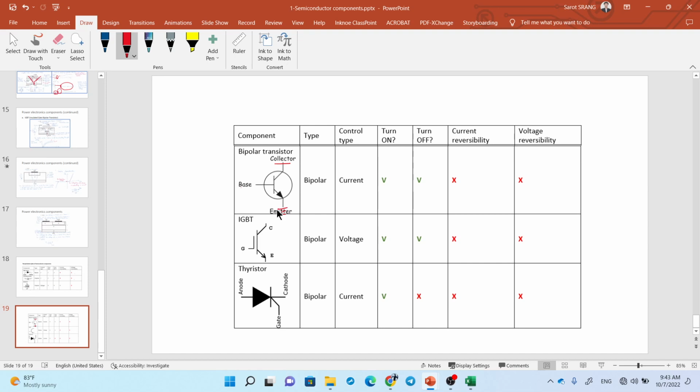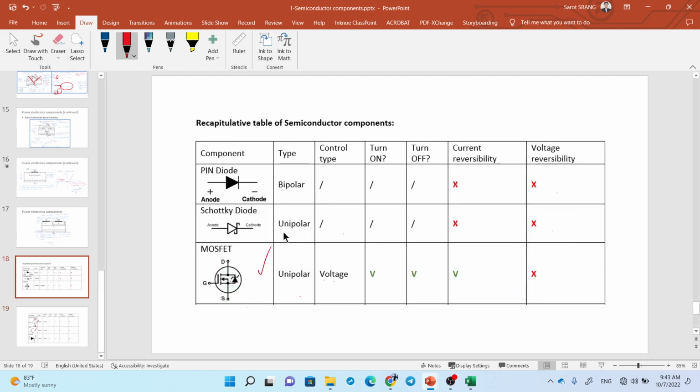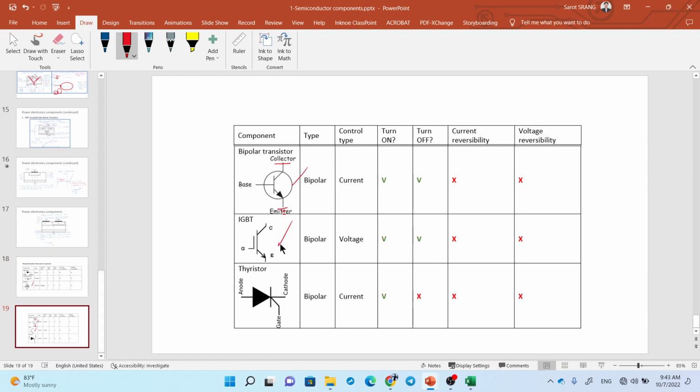But in some cases, you use this kind of extra circuit in order to have the right condition to control higher power components like FET or IGBT, right? So this one is for high power, this one is just low power for small electronics. MOSFET is also for higher power, but not very high, it's medium, but IGBT is for the highest power.